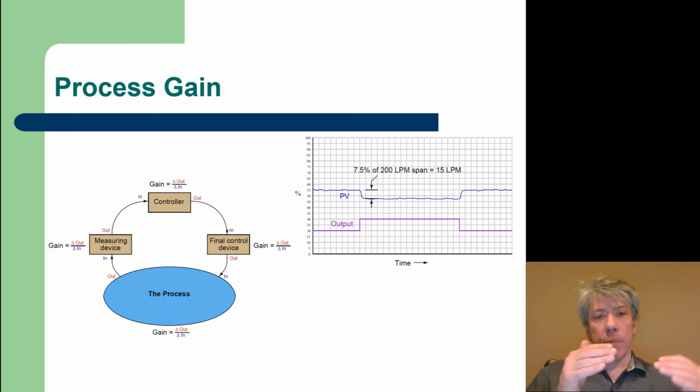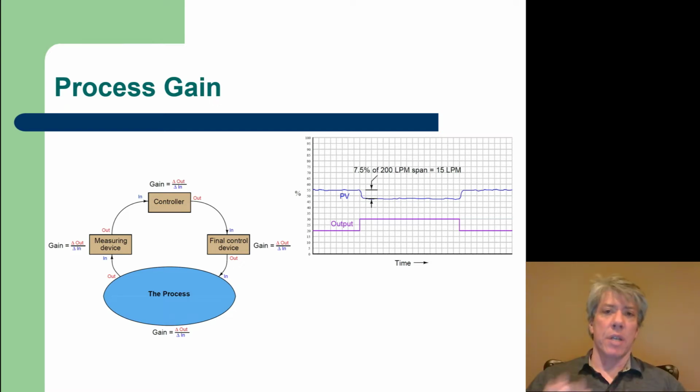So the thing that comes into the controller is a percent signal, and what comes out of the controller is a percent signal. Now, how does that work? Because the control device is a pedal. So how do you decide? Well, the pedal could be all the way released or all the way to the floor, right? All the way released would be 0%. All the way to the floor would be 100%. Halfway in between would be 50%. So this idea of percentage brings with it a calibrated range, a range of operation that we don't intend to go past, or no, we cannot go past.